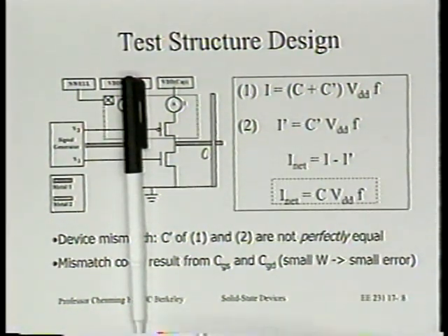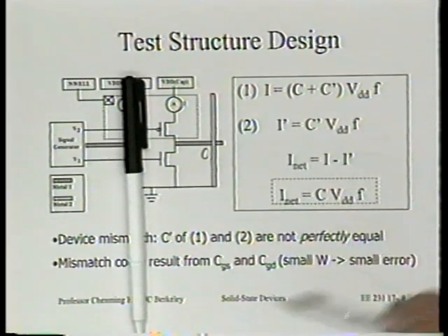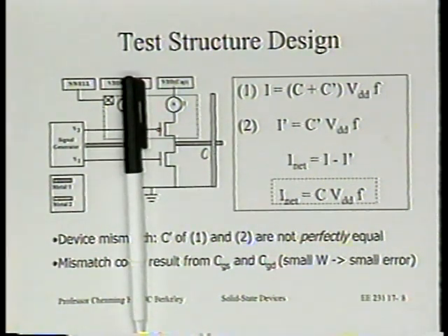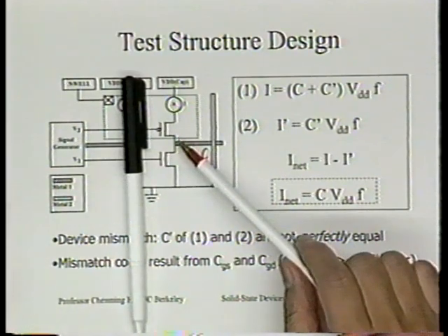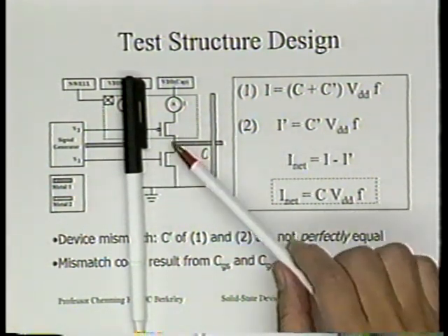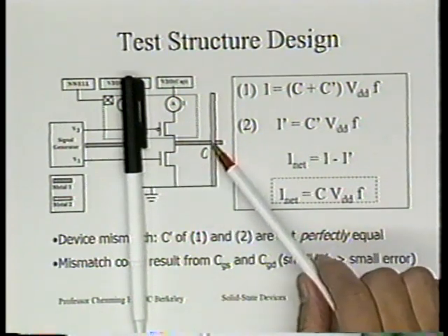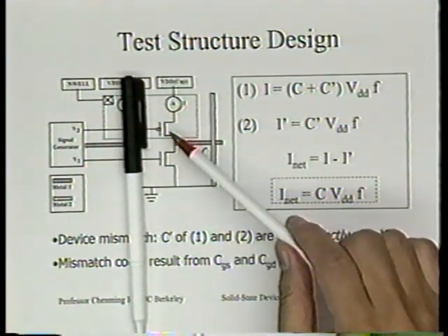You see, we're using the same concept used in the last lecture about how the inverter works, right? So when the p-channel is turned on, current flows from the VDD to charge up this capacitor. You wait long enough, because we're not trying to build a gigahertz chip here. You can use only 1 megahertz or even slower if you wish. You wait long enough to make sure it charges to VCC or VDD. Then you turn off this P transistor.